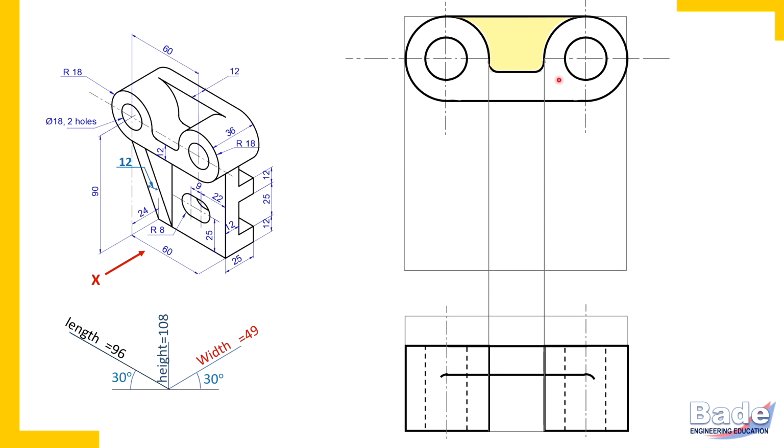I have erased edges here, check here and here also. So necessary correction you will have to do. Remember, when two surfaces meet in one single plane, then the boundary between the two surfaces you will have to trim out.